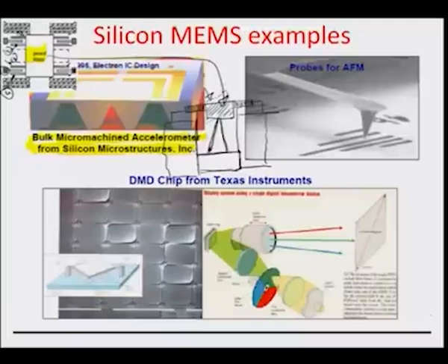And so, there is always a change in the interfacial area between these wings which are there on the proof mass, and the metal structures which are printed onto the otherwise plane surface. And because of the change in the interfacial area, there is always a change in the interfacial capacitance. And because of this capacitance change, there is an electronic signal.